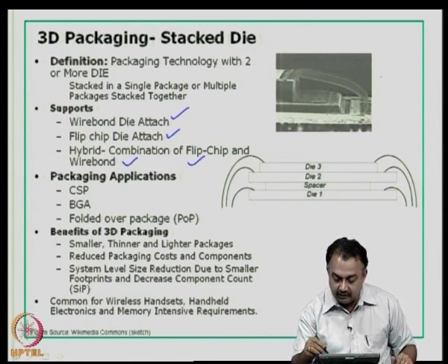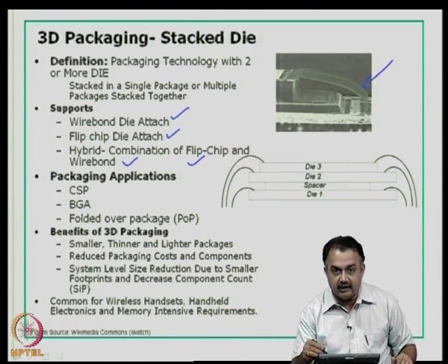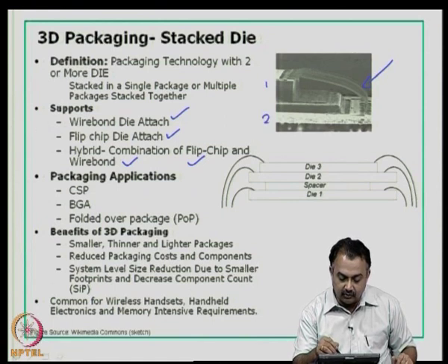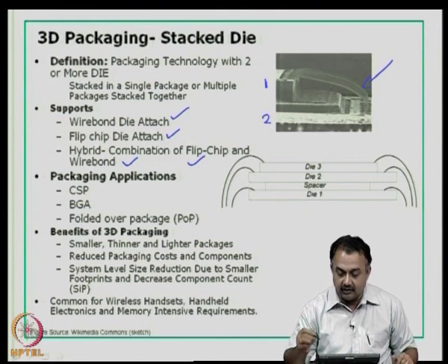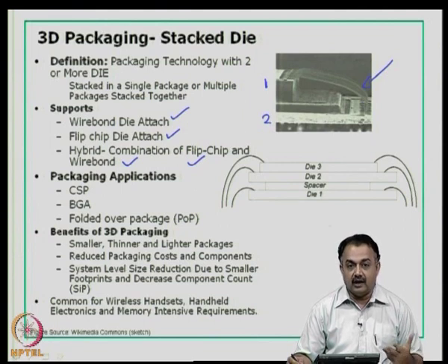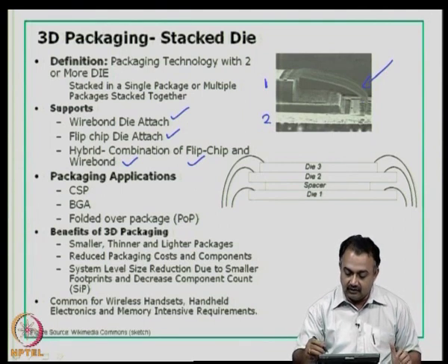If you look at this picture here, you could have these wire bonds coming over here onto the base die, coming from the second die. So, you can have die 1 and die 2. The die 1 is sitting on top of die 2 and interconnected to the base die. Both the die, or 2 or 3 dies, can have a common substrate onto which the interconnections are made.